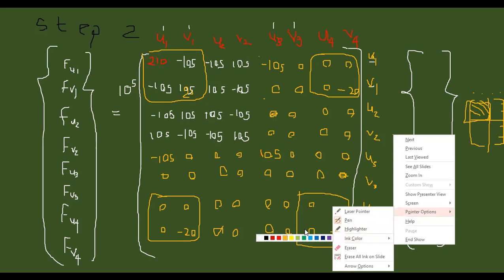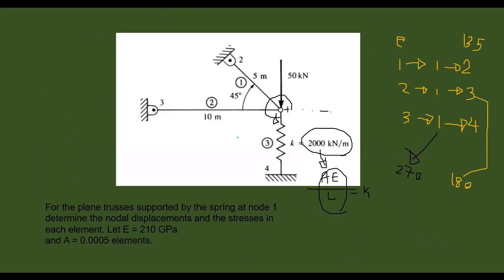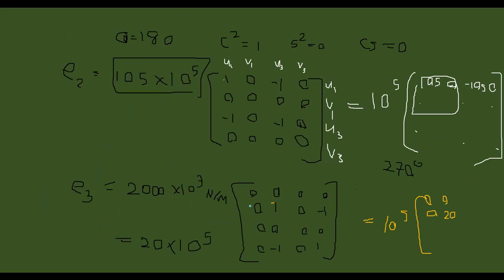And these are for denoting. So this is the displacement matrix, the correct one, u1, v1 up to v4. You will see something, right? These are supports, pin support, pin support, pin support, right? That means the u and v displacements at nodes 2, 3, 4 are 0 because there is a support.